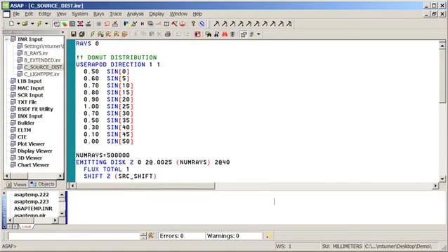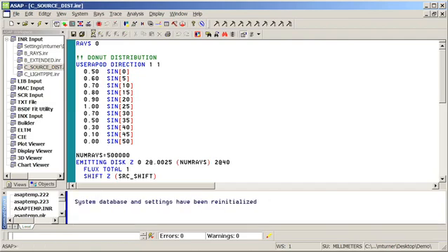The third type of optimization available is simulated annealing. Simulated annealing is appropriate for those situations where you, for instance, might not have a continuous solution space, or you might have to search over a very large solution space to try to find the answer. What we're going to look at in this case is a problem where we're going to optimize for fiber coupling efficiency. But in this particular case, rather than having something like a simple point source, we actually have a directionally apodized energy distribution. I want to show you what the energy distribution looks like so you can see the complexity of the problem we're solving.